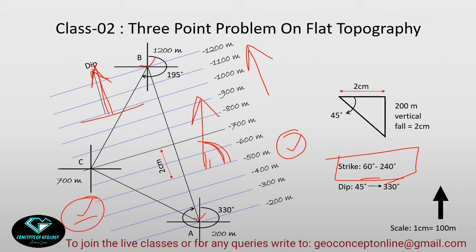What will be the value of the dip direction? You can measure it, or you can say it will be perpendicular to the strike line. So if this end is 240 degree, then the dip direction will be 240 degree plus 90 degree, that means 330 degree. So that means the bed is dipping towards 330 degree, towards the northwest.